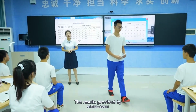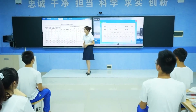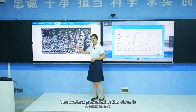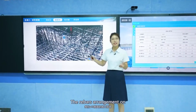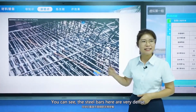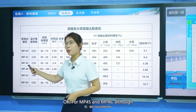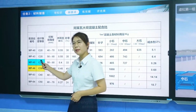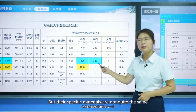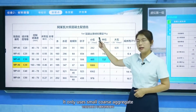The results provided by these 2 groups are different. Which group is correct? Let's start by watching a short video. The content presented in this video is the rebar arrangement on the construction site of A13 block. You can see, the steel bars here are very dense. Okay, for MP45 and MP46, although their strength levels are the same, their specific materials are not quite the same. In MP46, it only uses small coarse aggregate.